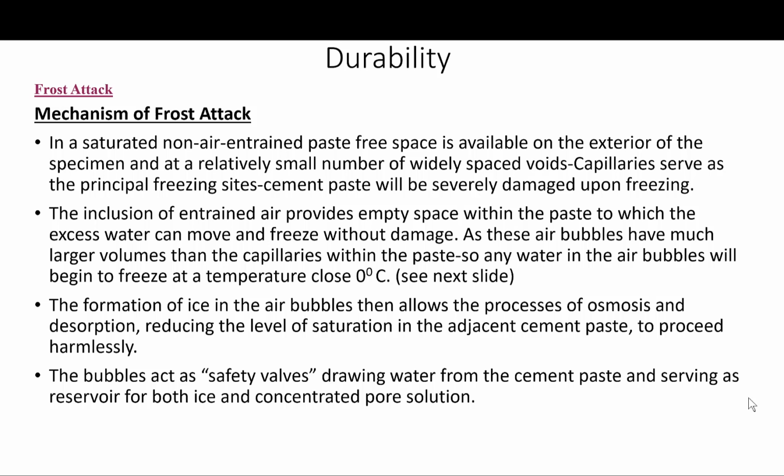So the bubbles basically act as safety valves, drawing water from the cement paste and serving as a reservoir for both ice and concentrated pore solution. So this is really the power of providing entrained air bubbles within the cement paste or within the concrete, where frost attack is a potential.